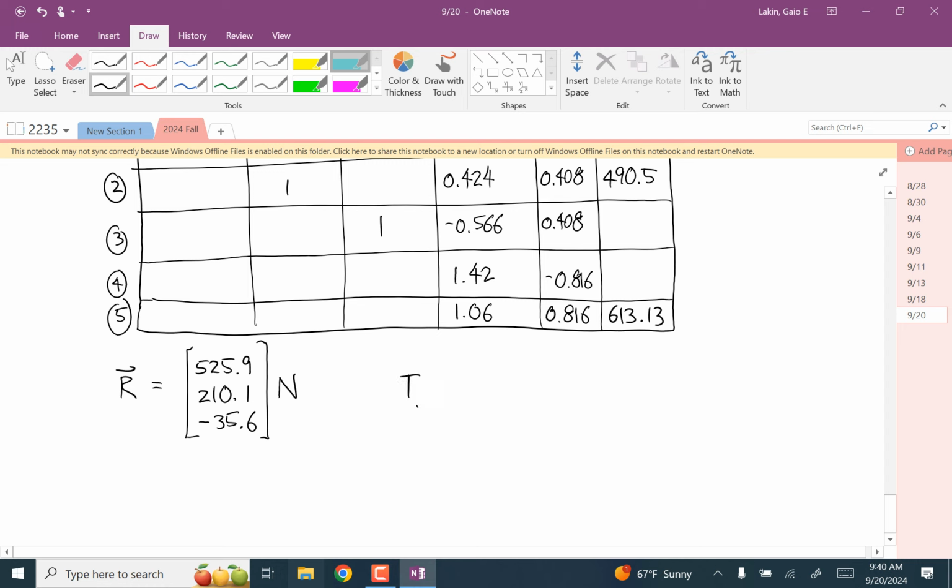And then T1 is 247.2 newtons. And then T2 is 430.2 newtons. And then based on that, you can tell what materials you need to use for those joints, what you have to attach, say, that ball and socket joint to, what you can use for those cables. This is super important information when you're designing a machine or system or whatever.